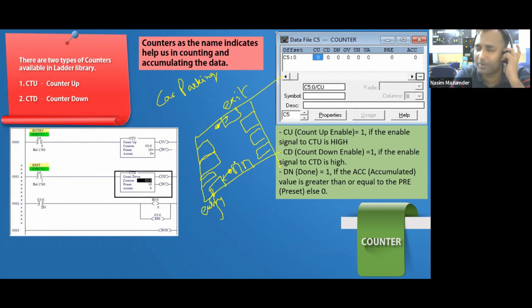So by any means there are 10. Now the moment I have connected this particular sensor here in my channel number 1, and this is what entry input 1, I:0/0, means. This sensor I have connected to the channel number 1 of my PLC, isn't it?